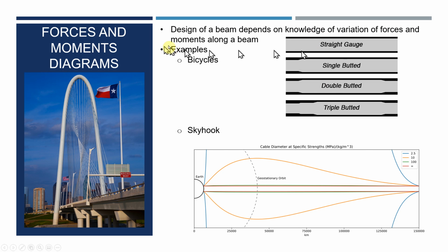That bicycles, for example, they want to be as thin and light as they can. So if you had a tube wall thickness that's constant, it's going to add more weight. But when you do this, you can put extra mass where the forces are the highest, and then reduce the mass where they're lowest. The overall goal being to reduce the weight of a bicycle.